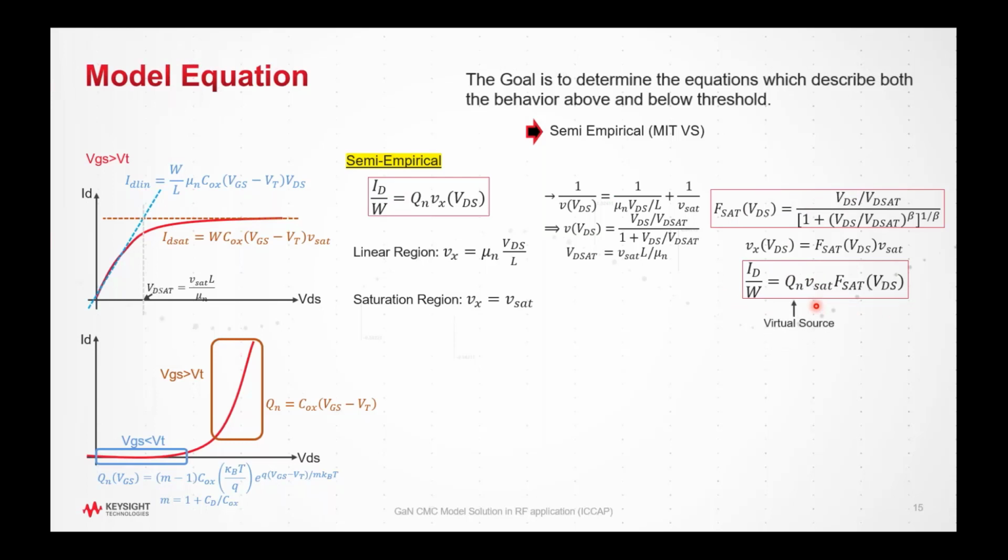And this virtual source usually sits at the maximum of the band gap in the band diagram. We also assume the velocity is the peak velocity, which also appears at the virtual source position. So these are the virtual source equations.